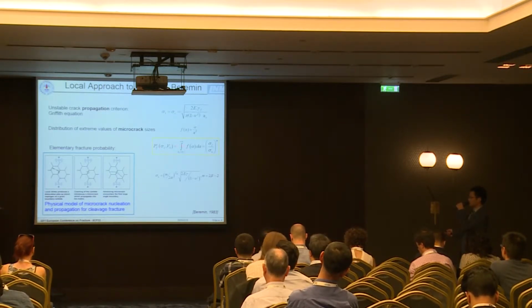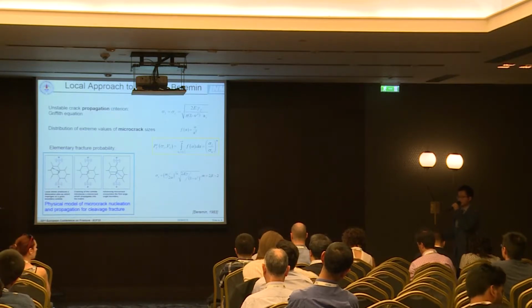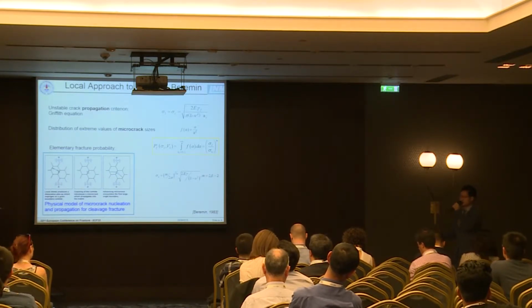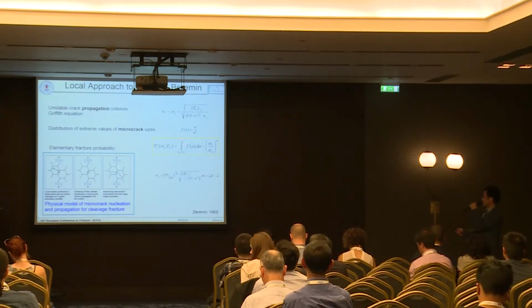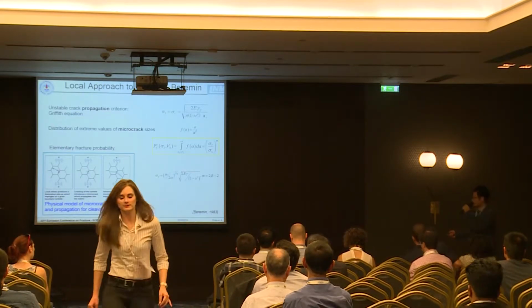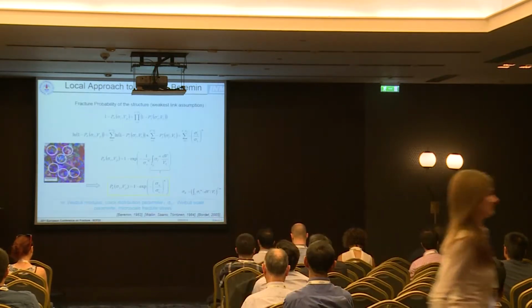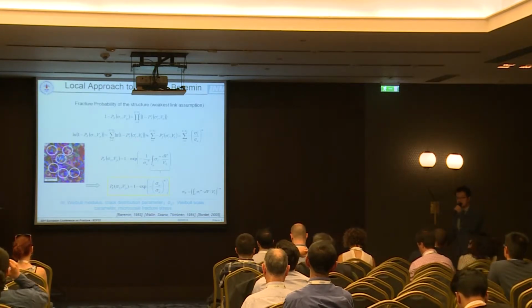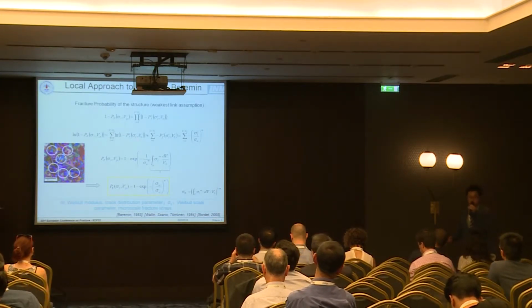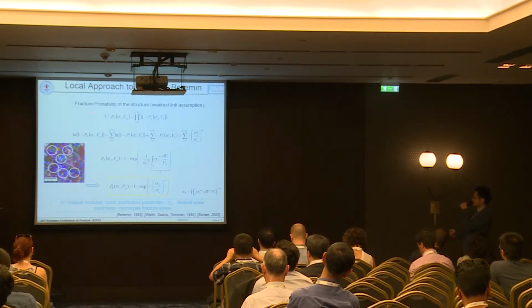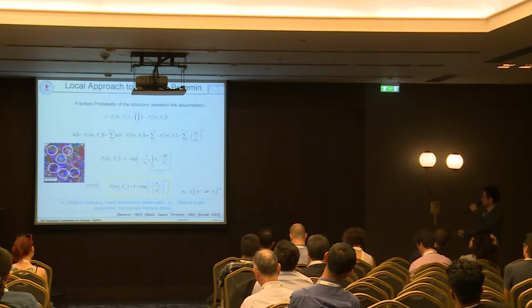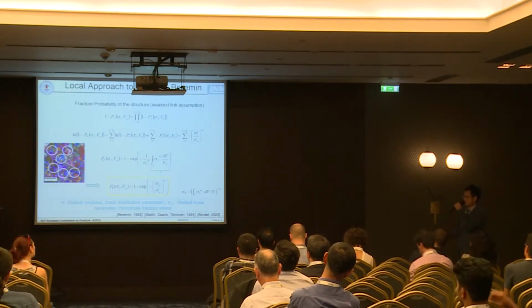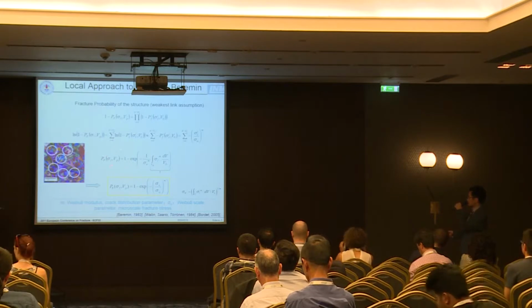Here, the probability of fracture is the probability of finding a crack which is larger than the critical crack depth. But it should be noted that the upper bound here is taken as an infinite value. Then, according to the weakest link theory, which means that the weakest part of the material determines the strength of the material, the structure consists of a lot of small volumes, and in each volume there may be a crack that follows a power law distribution.